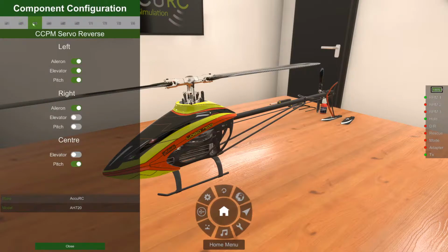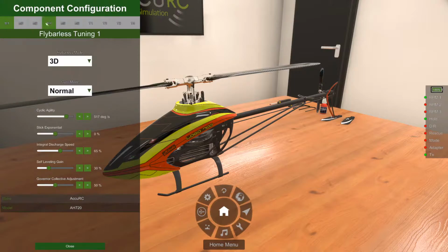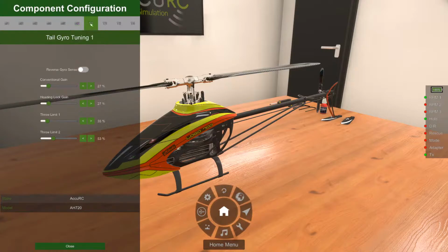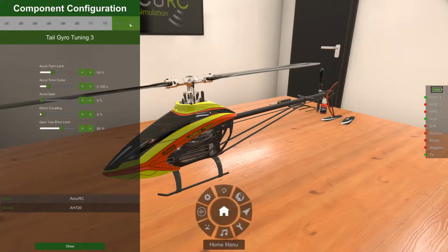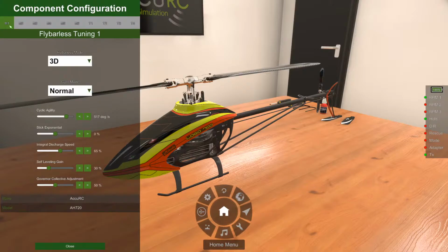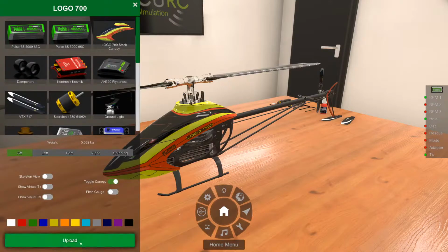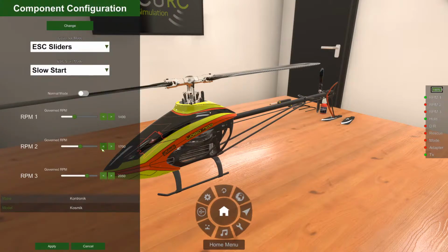All right. So it also results in, and you can see the circulation right there at the leading edge. You can see the circular motion of the air, of the fluid in this case. And you can see just behind the trailing edge, there's another one. And what has just happened here is that the airfoil has just started moving, and it creates a startup vortex, and it gets left in the air. I've heard of people on certain days, on foggy days over at LAX, just as the aircraft rotates and starts to create lift, you can see the startup vortex start. And it just sits there as the airplane flies away. And there's this startup vortex that's left circulating just above the runway. So these sorts of things actually do exist.